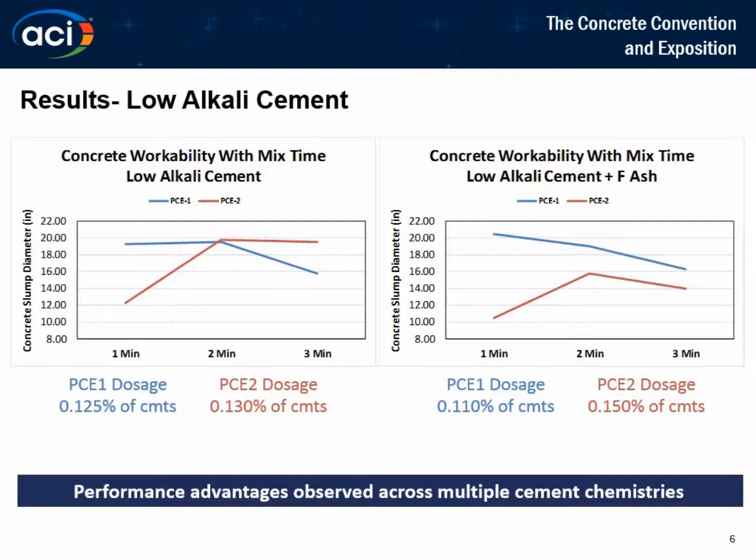So as a follow-up, then does the fast wet out result in an overall reduction of mix time? Because here you would still need to mix 3 minutes to see what the final workability is. If you discharge that at 2 minutes... Could you ask that again? So the total mix time, even though you wet out faster, does the total mix time get reduced? Because here, at 3 minutes, you actually had less workability, so do you need to leave it in the mixer for the same length of time?